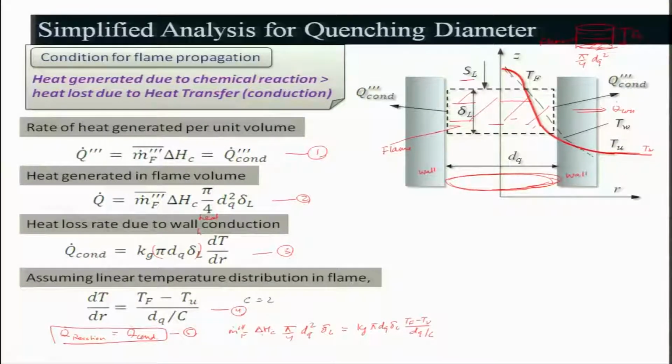So, if I look at this delta S C, what is delta S C? Delta S C we know is equal to nu plus 1 Cp into Tf minus Tu, right. Are you getting it? In that case, I will substitute this here, and in place of this I will write nu plus 1 Cp Tf minus Tu.